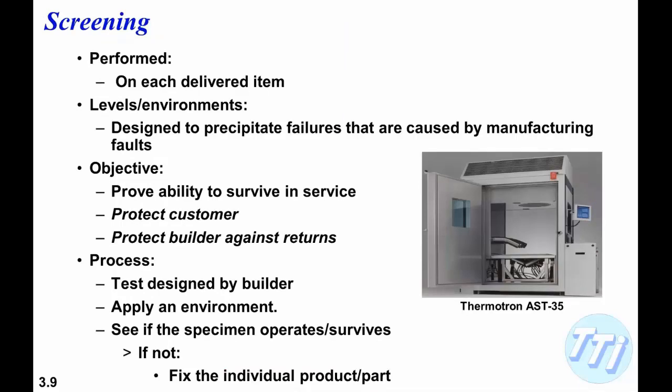Screening is performed on each delivered item. This is obviously set up for mass production. The levels are designed to precipitate failures that are caused by manufacturing faults, and we'll talk about that more later. The objective is to provide the ability to prove the ability to survive in service, protect the customer, and primarily to protect the builder against returns.